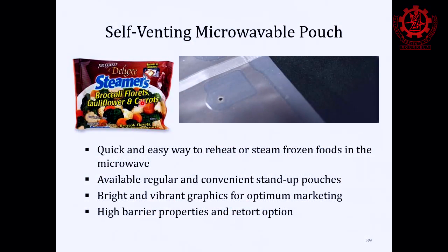Then what happened, if it has a high moisture, it's going to produce vapor. If you heat it a few minutes extra or few seconds extra, the vapor pressure would be way beyond its seal and it's going to blow up. So this happened a few times. Rather than teaching the consumer to please read the instruction and follow it, engineers like you thought, rather than having burden on the consumer, we will help the consumers. They came up with this technology where they had this valve on the pouch which will open when the vapor pressure inside reaches a certain level.